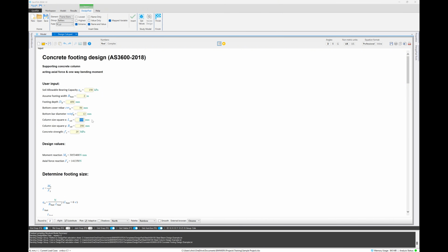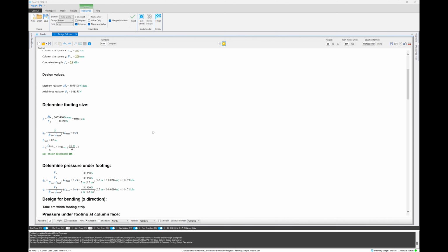You know, in this case it's going to be 200, sorry, not 250. So we had columns there of UC 200, so we'll make that 200 and 200, and we'll hit the play button and see what happens.